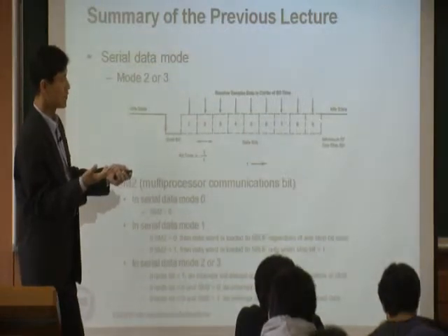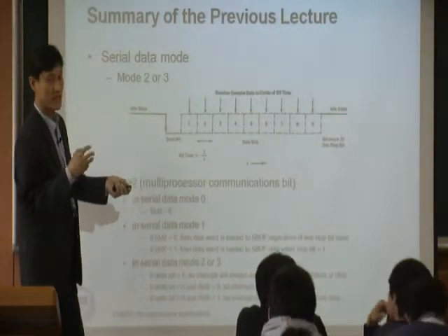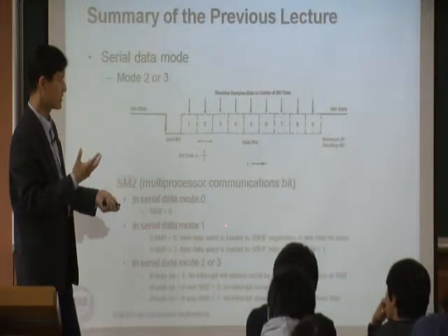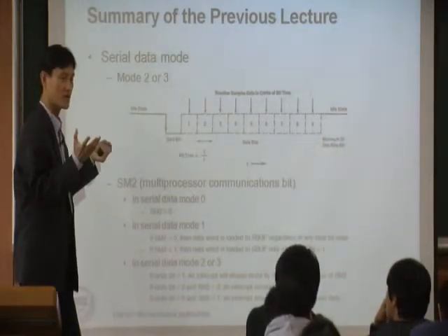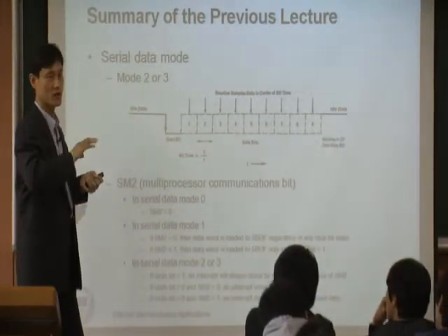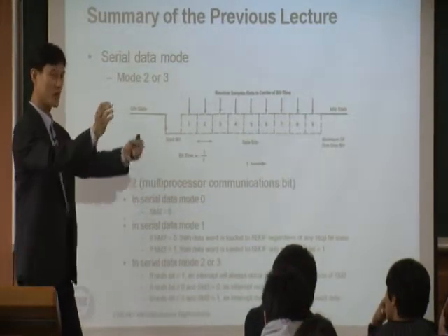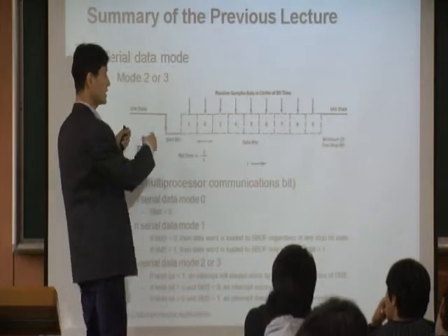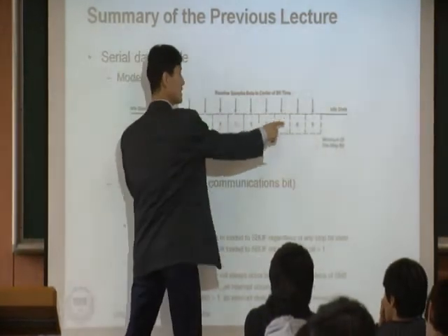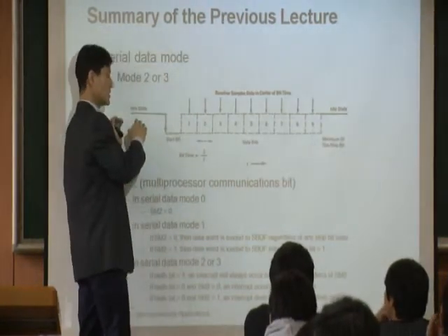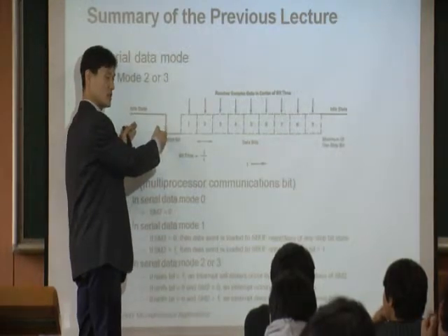So the stop bit may go down to 0. That's actually an error case. When you have an error, I'm going to drop whatever letter I receive. Let's say I'm a receiver, receiving these bits. The first thing to do is check the edge.